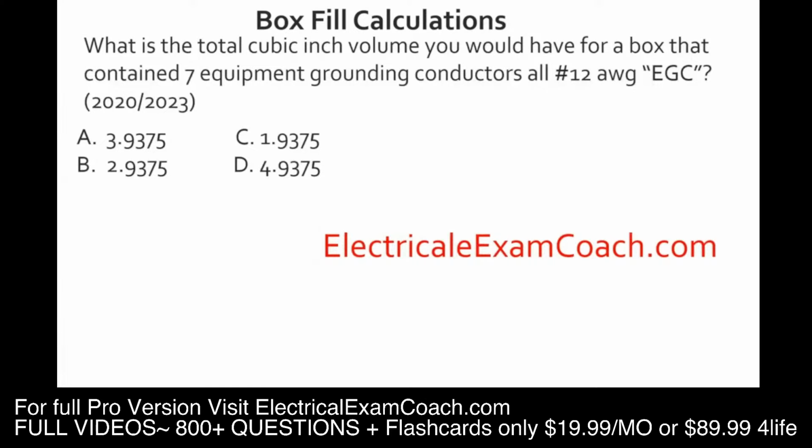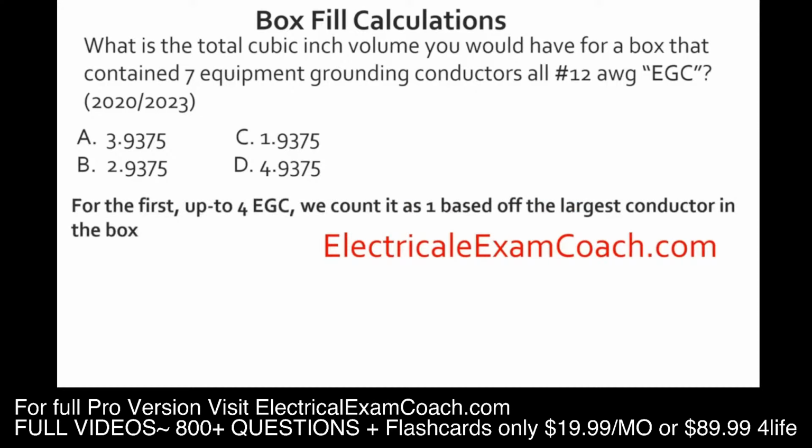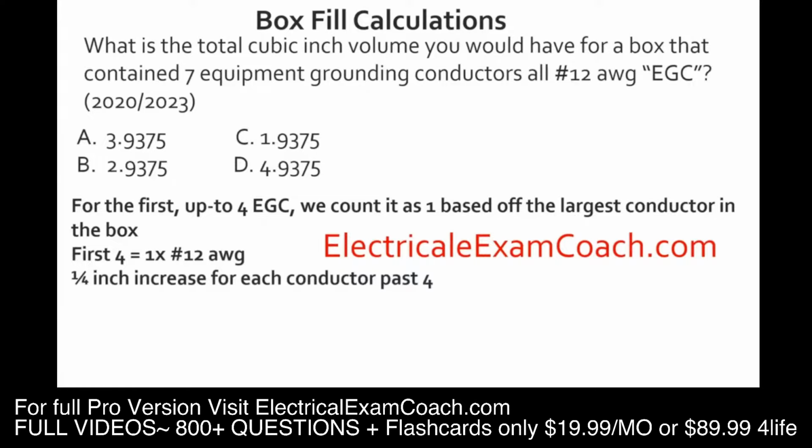What is the total cubic inch volume you would have for a box that contained 7 equipment grounding conductors, all of the 12-gauge persuasion in the 2020 and the 2023? I left out all other conductors because you're going to use the same rules in that after you do this calculation, you group it with whatever the largest conductor is in the box, like you learned previously. What we're going to do is count the first 4 and count it as 1. And then a 1/4 inch increase for each one past 4. Sounds complicated. We're going to break it down very simply.